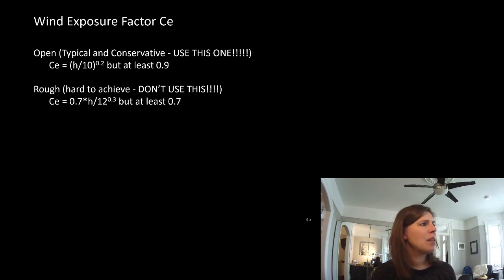The Duke of Argyll was the pub that was in it. That pub closed in like 2004, and they tore that building down in like 2010 I think, something like that. So the point though is that it can happen. As much as we're talking about long-term life for these buildings, it is not a static thing, and the environment around them can change. So unless you have a super darn good reason, and you would have to convince me otherwise, assume that everything around your building could be torn down and you'd have full wind exposure buffeting this building.